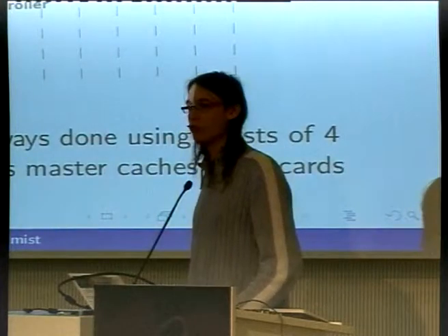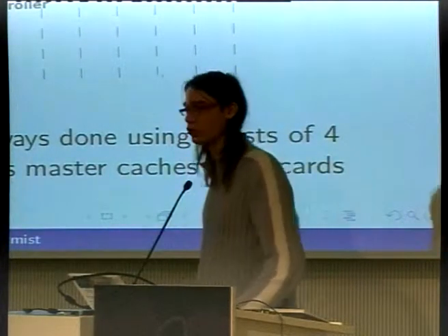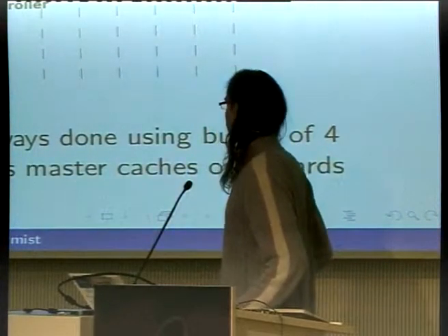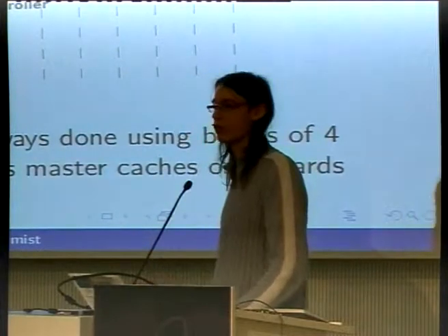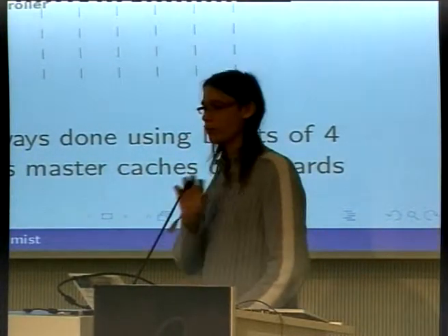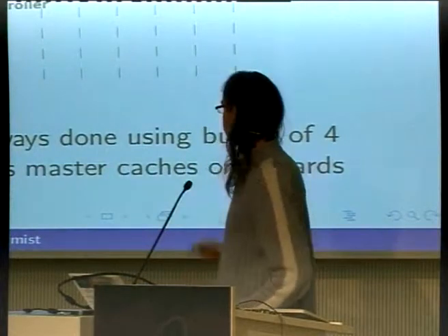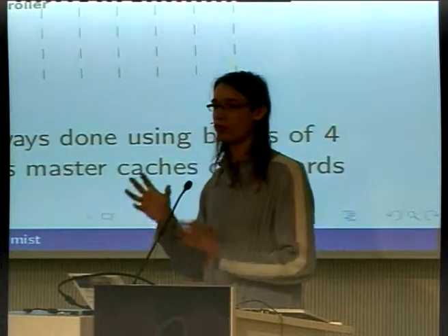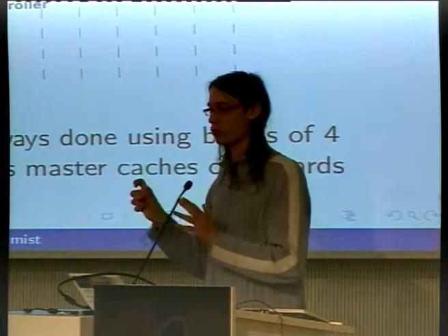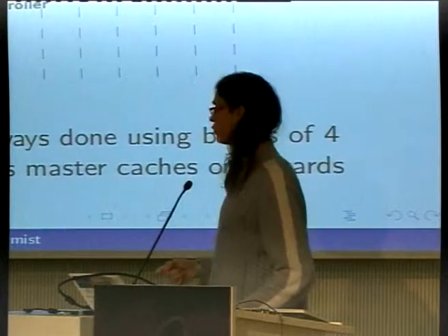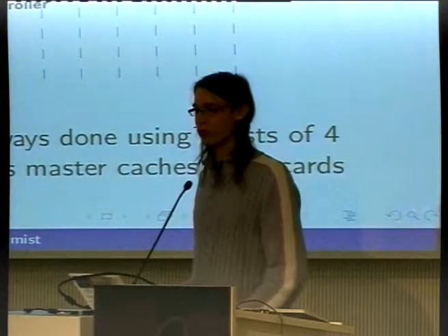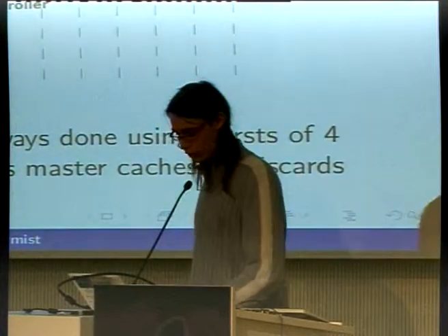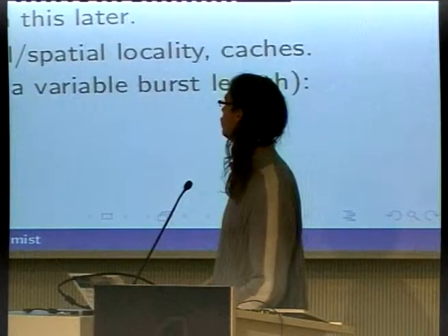But what you can do, which is a much simpler solution, which doesn't need an out-of-order CPU, is do something which is called bursting. Every time you do a memory transfer, you get the first read command, and then you read the consecutive words. And in Milkymist, I am using a burst of 4 words. So every time I request any word from the memory, the controller automatically requests the next 3 words. And I will then discuss how it could work, because it may seem a bit strange to do that, because you're not even sure if you're reading the next word or not. But I will then discuss that.